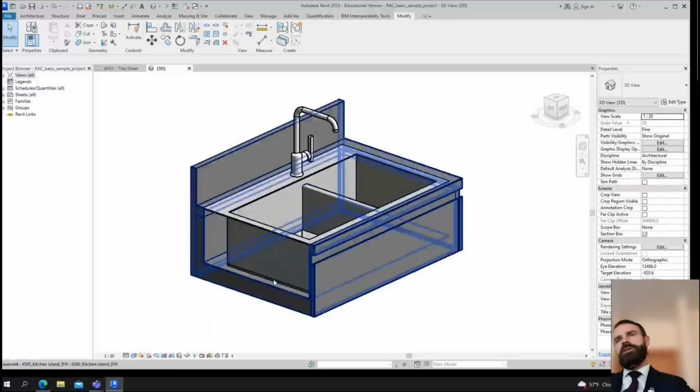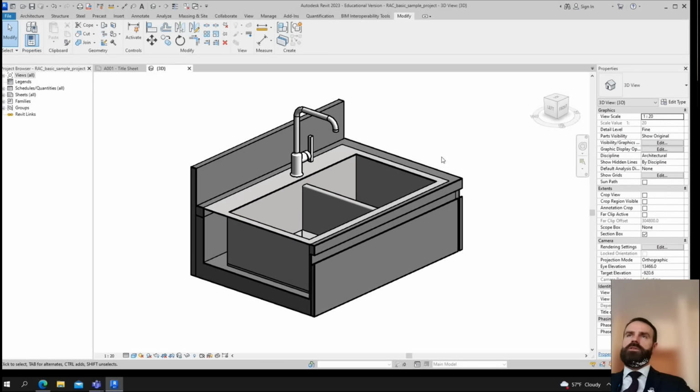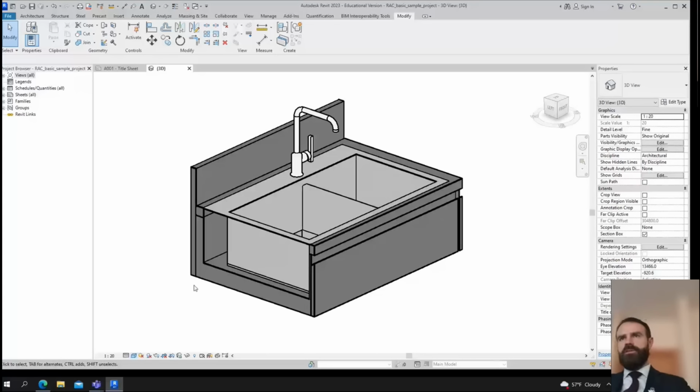If you use shaded, you can get some problems because shades will create images like raster drawings, and if you export the project to specific formats, maybe PDF, DWG formats, it will convert object not in the vector graphic, but in the raster graphic, and you will see raster elements in your drawings. So consistent colors is a good solution.